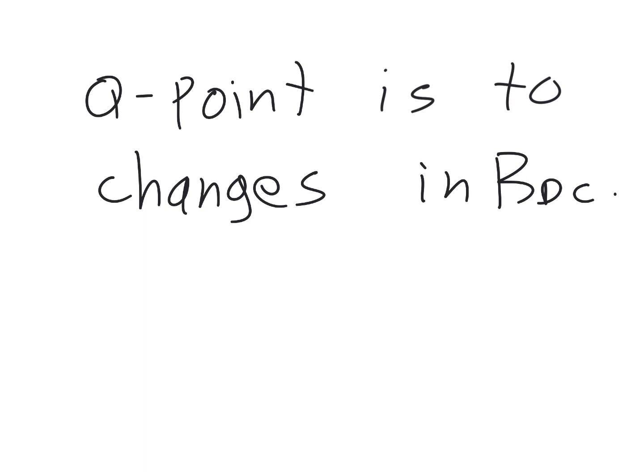And that it varies widely from transistor to transistor. And we saw that if you're up in the active linear operating range, that's sort of the threshold when VCE is greater than 0.7 volts. Okay, as I said earlier, it's a bit of a fuzzy line. It's not an absolute line, but that's what they call it.